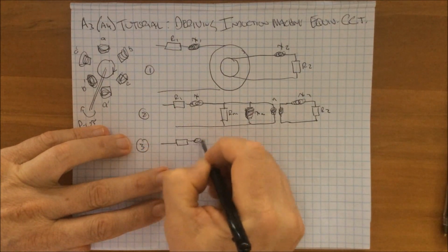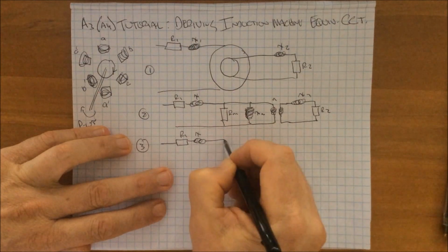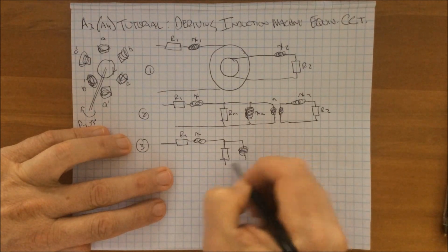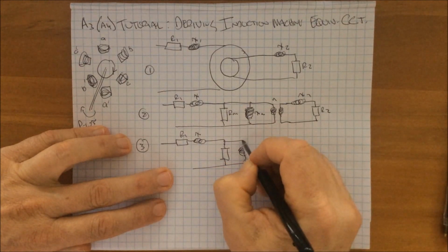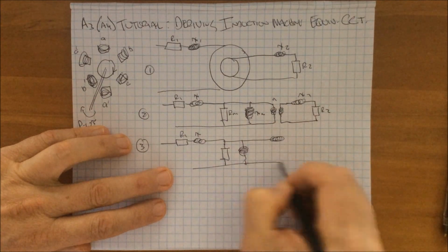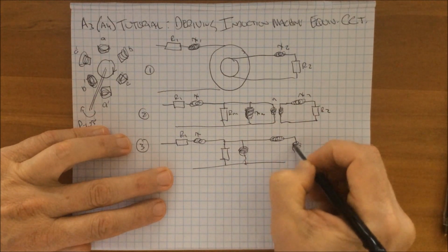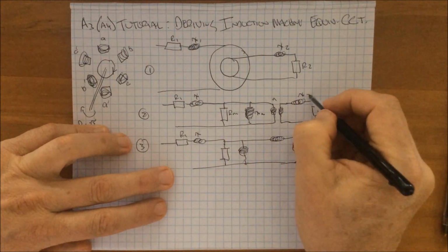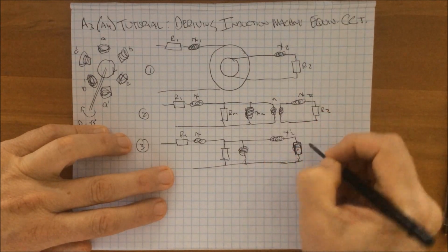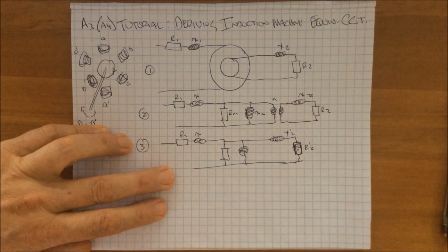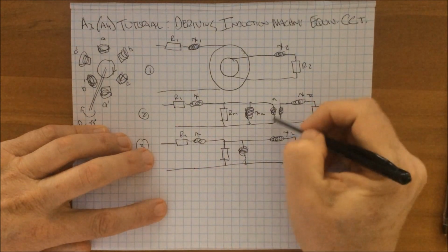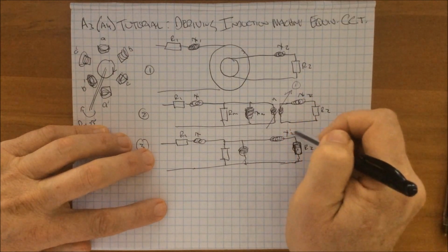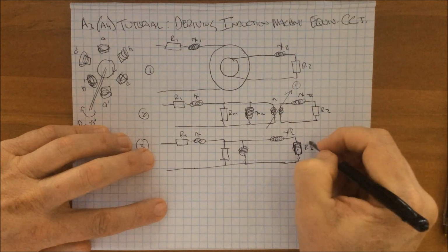Again, this stays the same, R1, X1, our magnetizing resistance, our magnetizing reactance. We're not going to have a transformer in there anymore. Oh, that's meant to be a resistor, sorry. And so instead of calling this X2, we call it X2 dash, and this is now R2 dash. So what we've done is we've got rid of that, and we've used the superscript terms here.